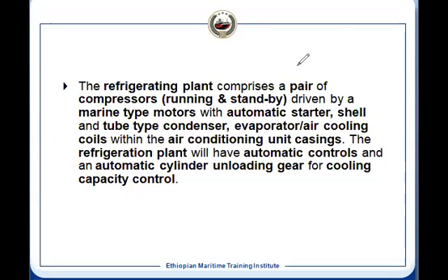It is the tube that can withstand the higher pressure because the diameter is less. But here the shell fluid is the refrigerant. The reason is that we need to do the maintenance of the water side, and the water side can be maintained easily because you remove the end cover and then you can clean the water side, the tube side.